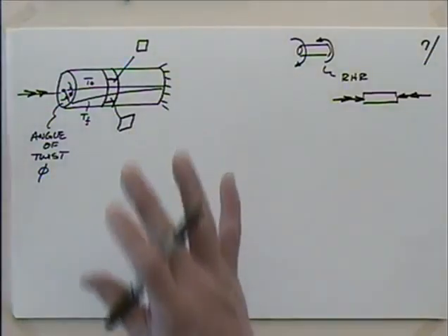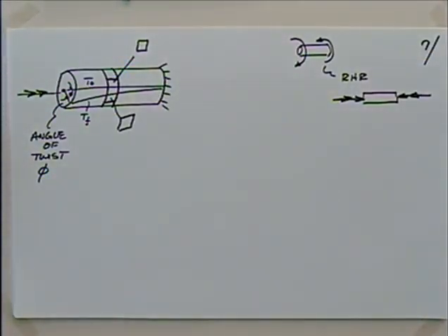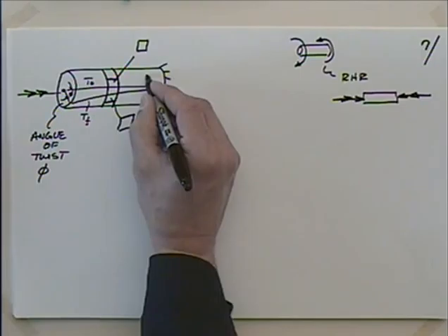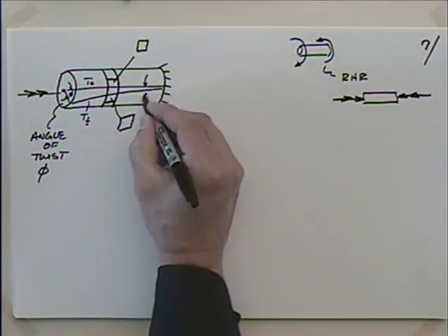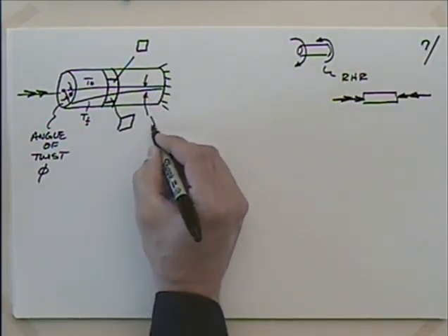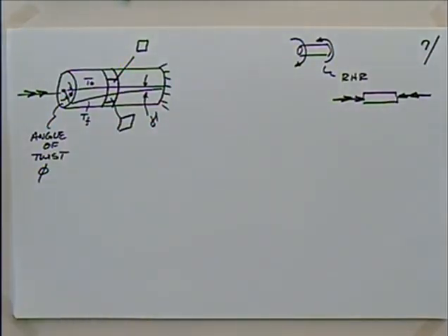When we talk about twisting this thing, we're only going to be talking about a couple degrees, at maximum, and we're going to be in the linear region where it goes back. But you can twist those shafts pretty substantially. Let me put this angle here. I'm going to say that this angle is the angle gamma, because that's how much our element has twisted.